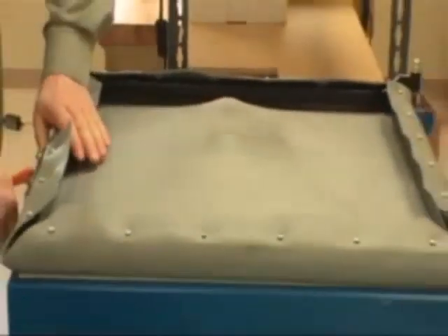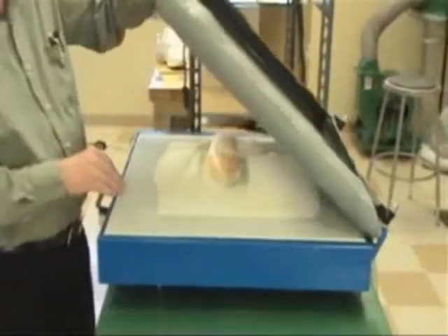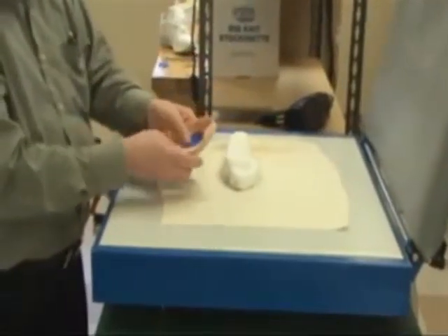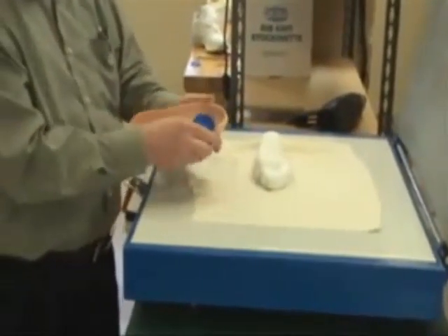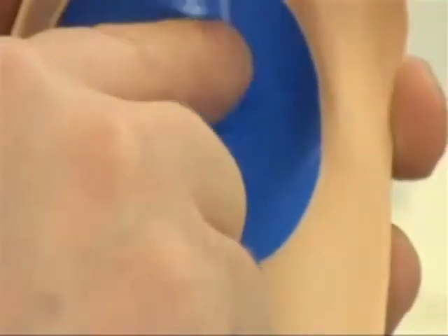Quickly place the accommodative footbed arch support or insole onto the mold and set the vacuum press. Hold vacuum for at least 5 minutes for the mold to cool, allowing the PSA and patch components to cool. The patch will be smoothed out very nicely and the edges recessed down into the foam material.